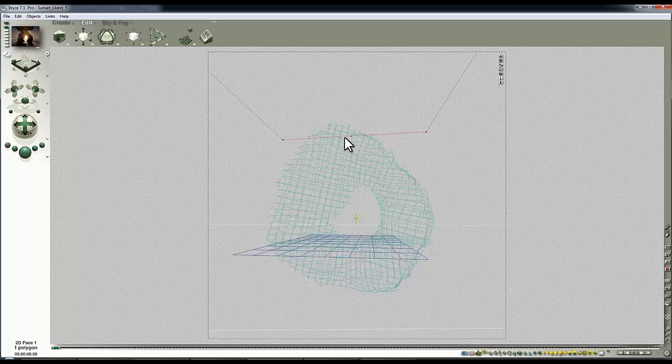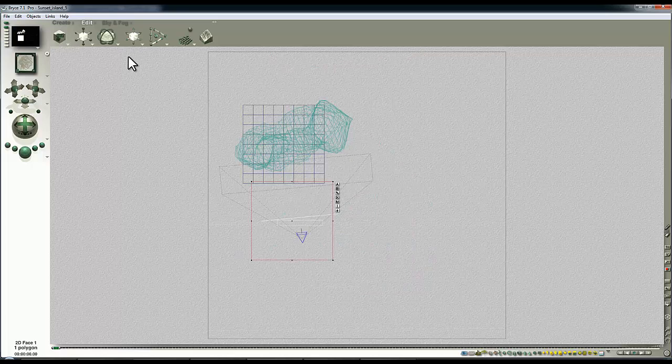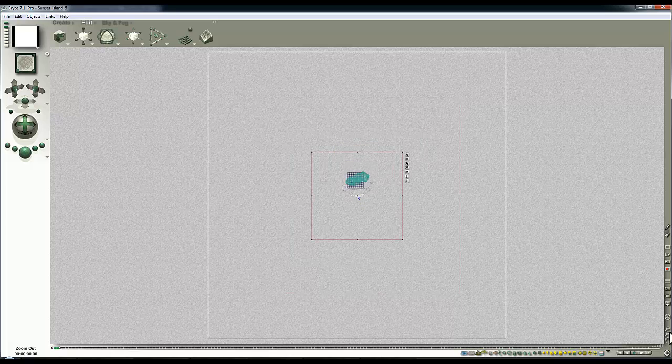So this will be the face that emits light if I make it a light emitting surface in Octane. Now, just looking in the overhead view, I want this to be some fairly general light, so I'm going to enlarge it a bit, but not as large as the 2D face that's the ground plane, because I've discovered if you make your light emitters too large, you'll put them too far away from your scene in Octane, and the light doesn't seem to come out. There's a sort of scaling issue, and I don't know what the answer to that is yet, and I've not found any settings. So I'm just placing this 2D plane.